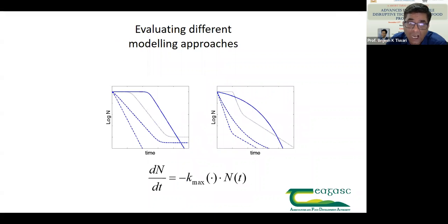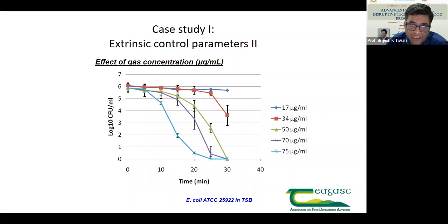Now, another one is how do we come up with the inactivation? We call it modeling, or curve fitting. So if you look at this particular inactivation profile here, you see there is a bit of shoulder here and then a further decrease, right? And then what will be the D value? Historically, we always use first order kinetics to get the D value, and possibly I might go to an Excel file to show how we can use different types of models to predict the D value.